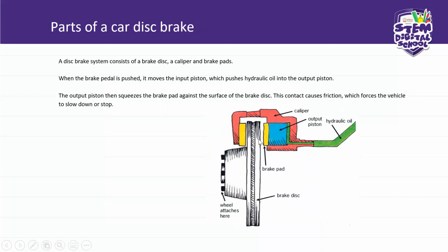the discs themselves. So if a car has not been serviced properly, like changing the brake pads on time, you will see that there are friction lines on the brake disc that show that the brake disc was interacting with the caliper and the brake disc will be worn out. So to protect the metal and also for the safe operation of the car, the brake pads have to be replaced at all times.